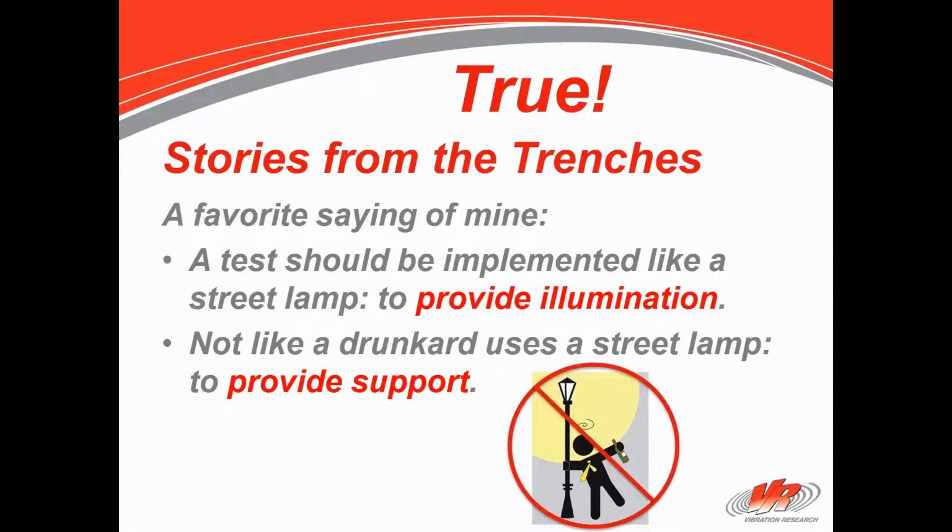So the question is, how do you know where the resonances are? Well, a couple ways. Very good question, a couple ways. Number one, you can hear them. If you're running a test and the controller draws a really nice line and it says everything is running good, but you're listening to it, you should hear just a nice whoop, kind of a smooth sound like that. But when it gets up to higher frequencies, if you start to hear yoing, yoing, yoing, something is resonating. And this is where controllers will have difficulty controlling because they're busy trying to keep that line nice and straight, and there's something in there that's banging, that's breaking into resonance and feeding back into the rest of the system, and you hear it because it's moving air molecules and it comes to your ears.